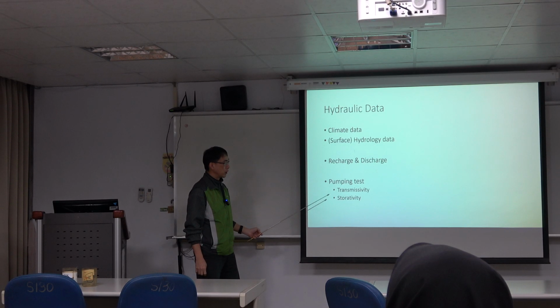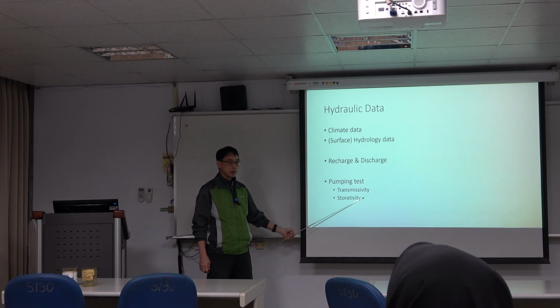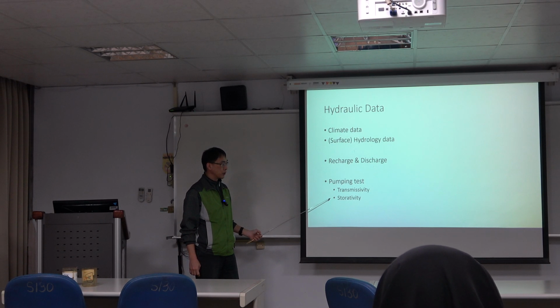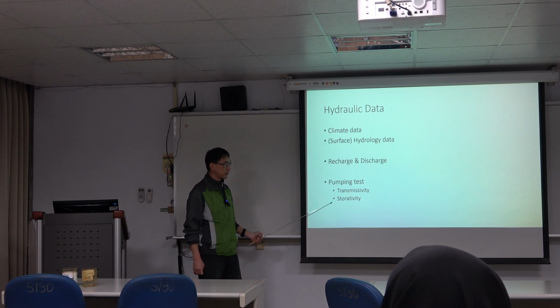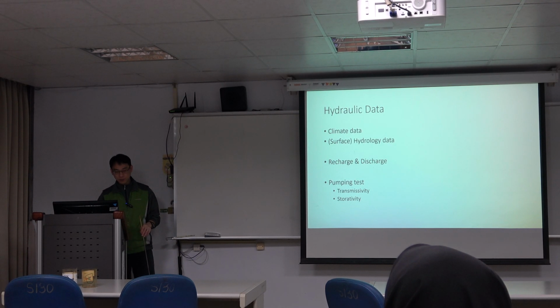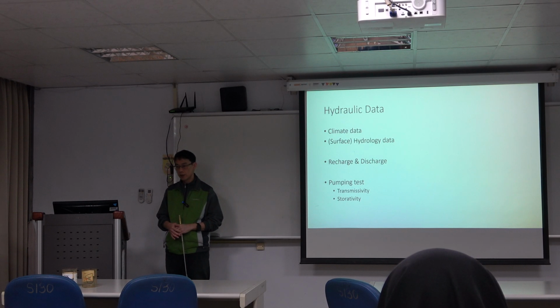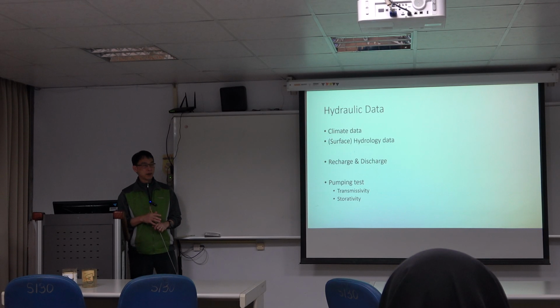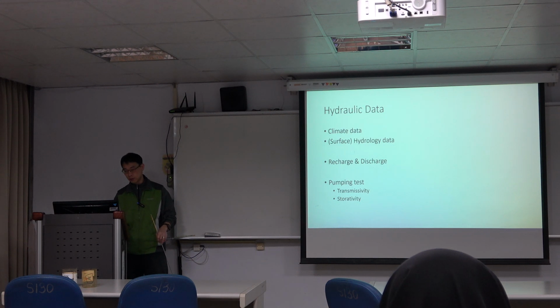And furthermore, if we would like to assess the properties of the groundwater system, we also need to conduct a pumping test. The pumping test is better able to provide the in situ quantity for the flow. So the transmissivity and storativity will be the two components we mentioned in the previous talk. We use the pumping test to estimate the transmissivity and storativities. So in the future lecture, we're talking about how to use the pumping test to estimate the transmissivity and storativities, and then how to analyze. We provide you the data, and then how to use the data to estimate the T value and S values based on the Theis solution.